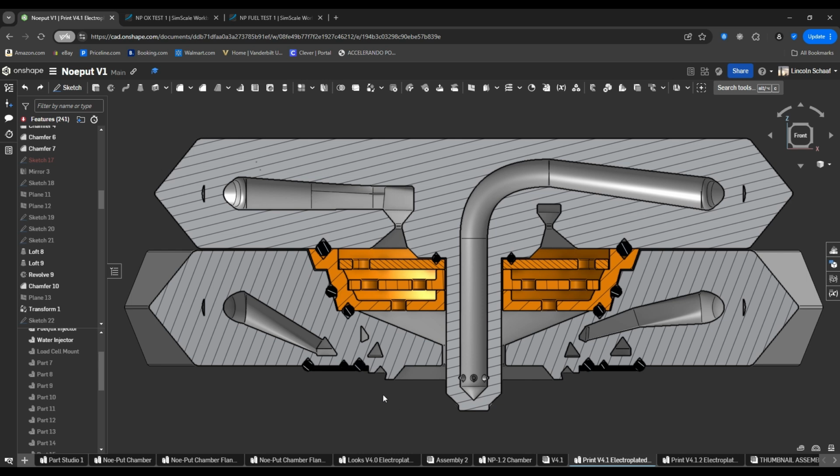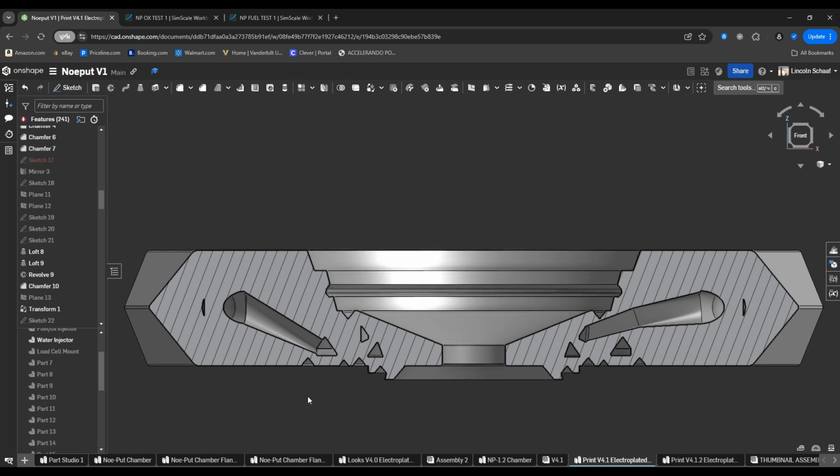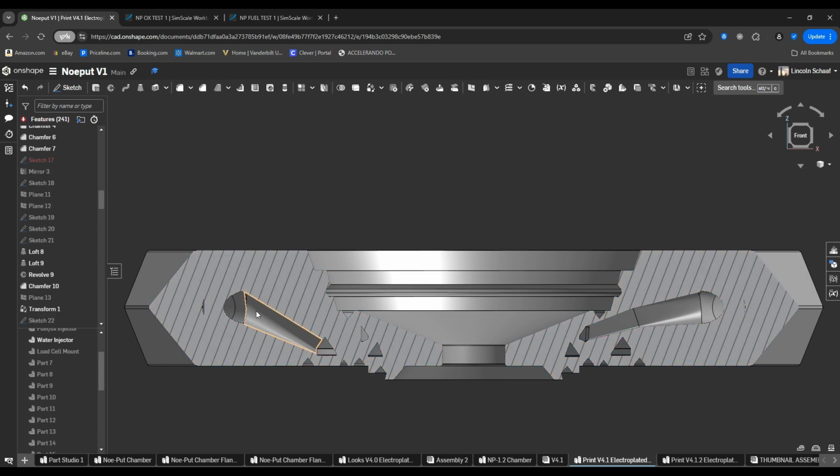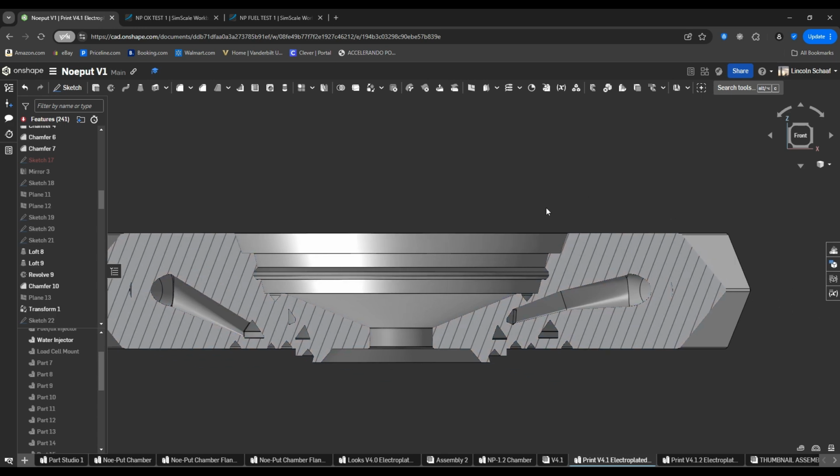powering the rocket. Now we'll move on to the coolant plumbing, which is water. So in the previous video we talked about multiple cooling methods, including regenerative cooling and film cooling. The water will be used for both. And as you can see here, it enters through two distinct channels and two distinct ports.